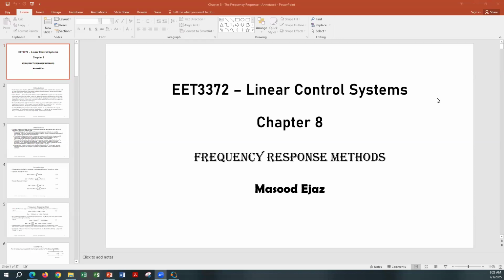For example, if you're setting a controller gain for the control system, and then when you start running your system, you observe that, hey, I'm not even getting that gain from that control system. And then you observe that you're not operating over the frequency over which you set that gain. So it's quite possible that your gain is not going to be what you plan to set, because your operating frequency is outside the range over which you are setting the gain.